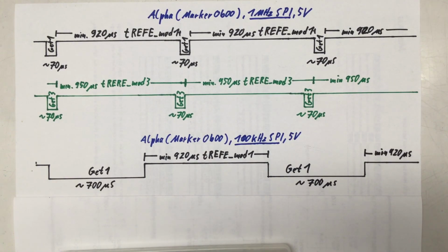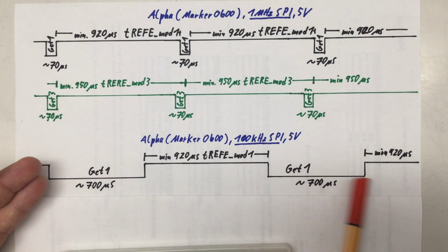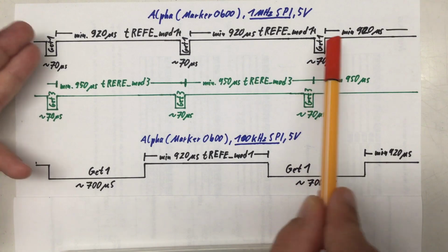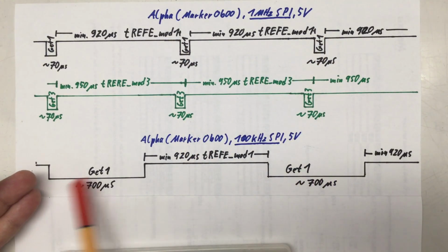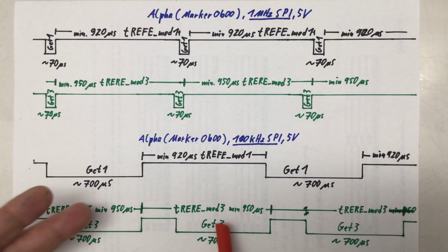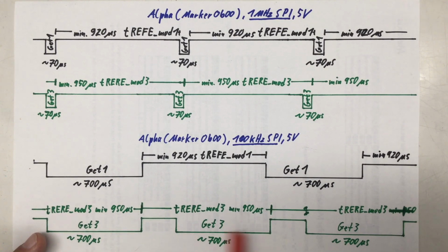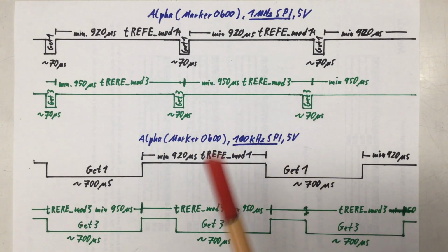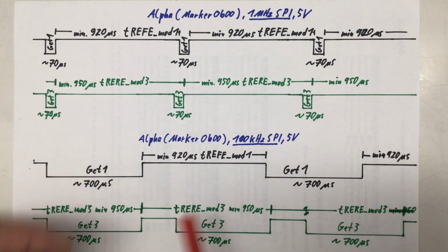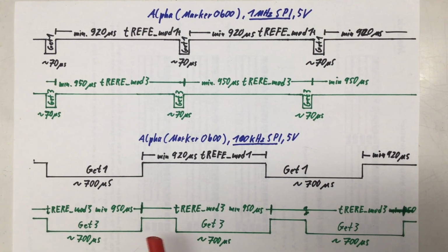And you can see that the frame rate compared to 1 megahertz gets much slower. However, in trigger mode 3, the frame rate stays the same. I get exactly the same number of measurements per second from my chip with the interleave, remember.